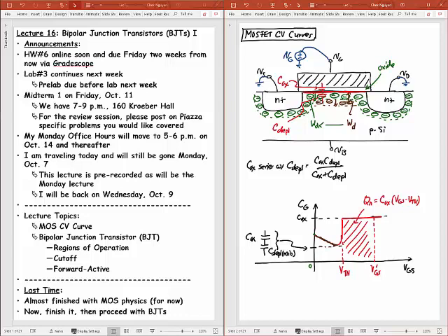Okay? And so this part right here, where I have this depletion region in brown, if I kept reducing my voltage, this thing would keep going up like this. And it will finally also get to Cox in a region that we're not really going to talk about in this class, but I'll at least name it for you. This is accumulation.